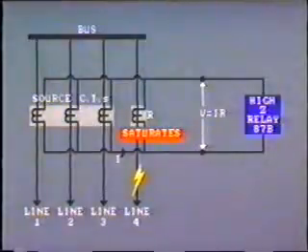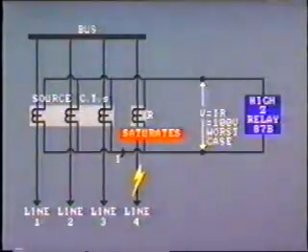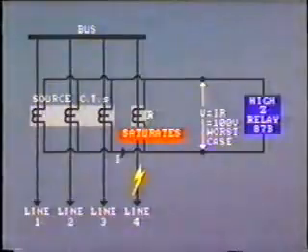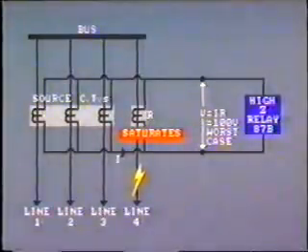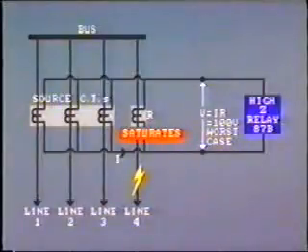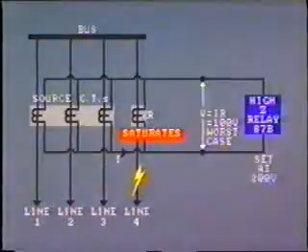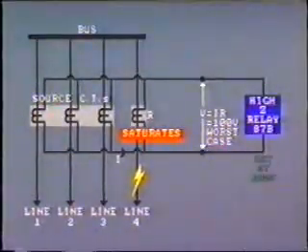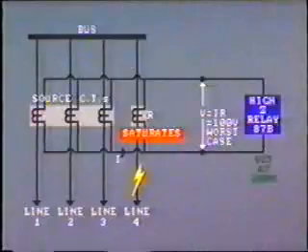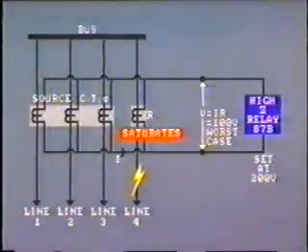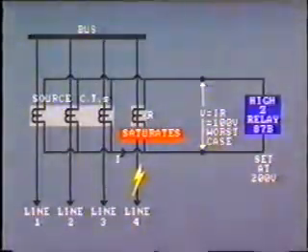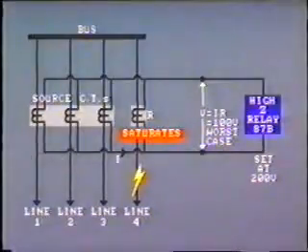Let's assume, for example, that the worst case or highest saturation voltage that could be presented to the relay was 100 volts. We would not want the relay to trip for this value. Therefore, we would desensitize the relay by setting it with a safety factor of 2, or 200 volts. The safety factor would have little effect on the relay's pickup for internal bus faults.